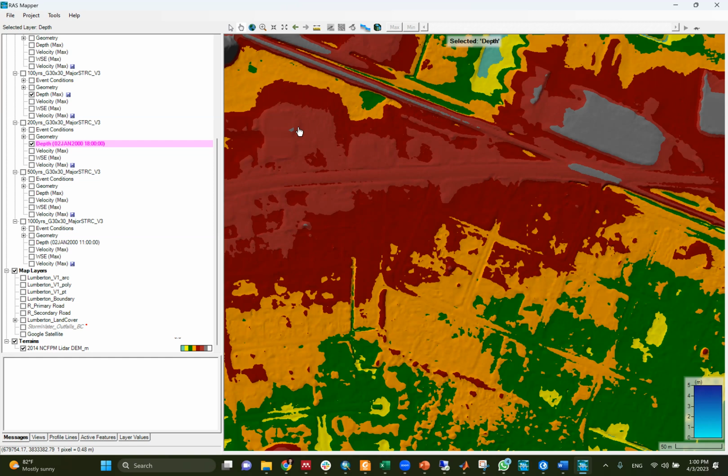When you convert it to a raster with the function in ArcGIS, it will ask you what pixel value you want to give for each one of these. I tell ArcGIS to take the pixel value from the number of stories or from the building height. It will give each block a value, the total height, okay? Then you merge this raster of the buildings with the raster map of the topography together. At each building, the ground will be replaced with the building block that has that raster value. So if this is the building here, it will remove what is here and put the new value of the building.